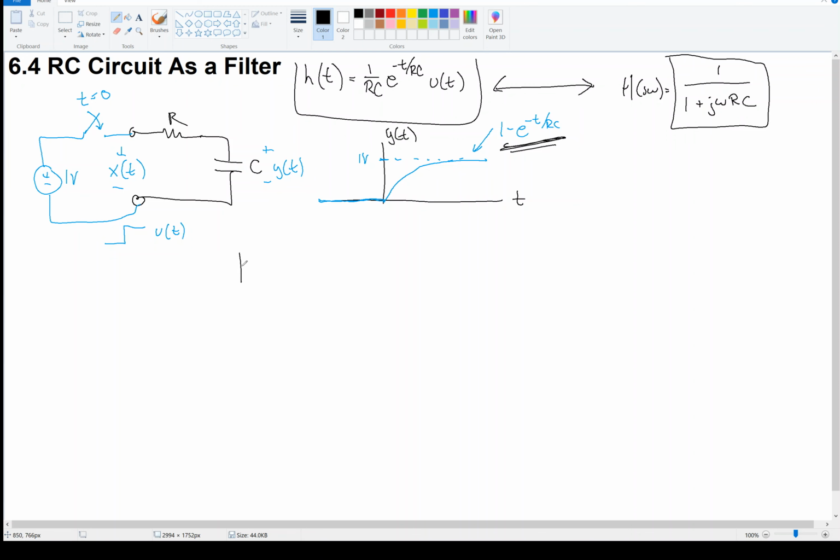So what we're saying in our class is we have this circuit, and it's linear because our resistors and capacitors are linear, and it's time invariant because resistances don't change over time. Capacitances don't change over time. So this circuit is linear time invariant. And we're putting in a unit step, right? The voltage was 0 and then became 1, and we want to know what do we get out. And we have the linear time invariance impulse response. It's this thing, which you can get from the frequency response. So how do we get y of t? Well, we convolve the unit step with the impulse response.